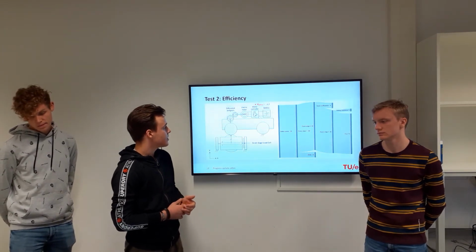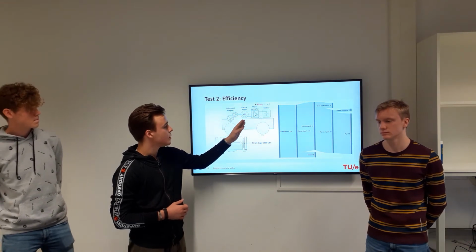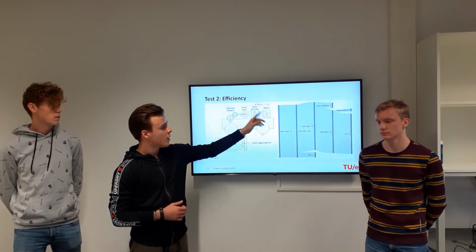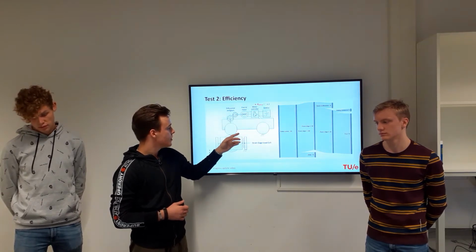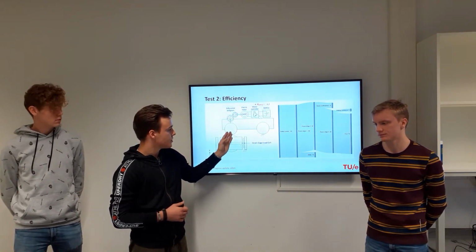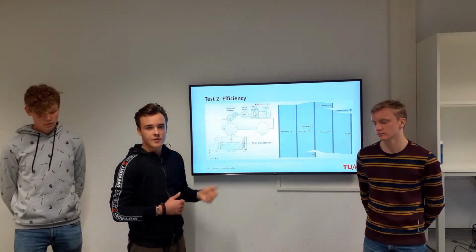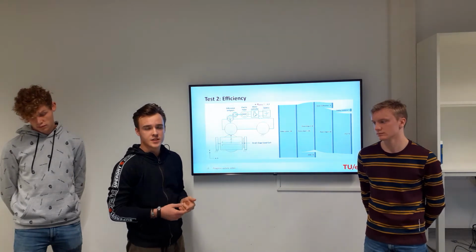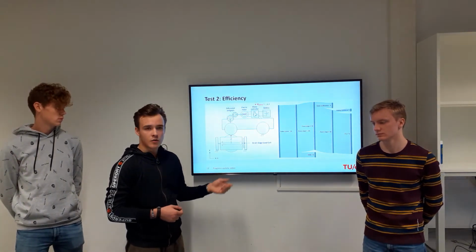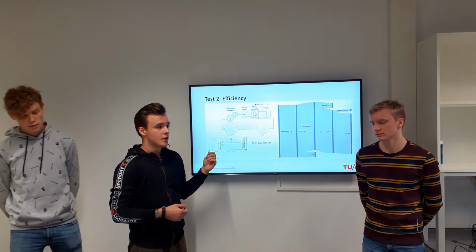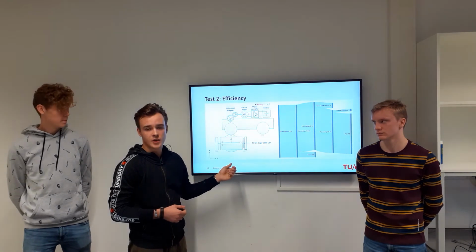This is the second test. In this, the motor will be turning. This will consume power from the battery. There will be an input. It goes through the drivetrain to the tires. These will be turning. The input power will be different from the output power. This means there is a certain percentage of loss of power through the vehicle, and this will be the efficiency of the total drivetrain.